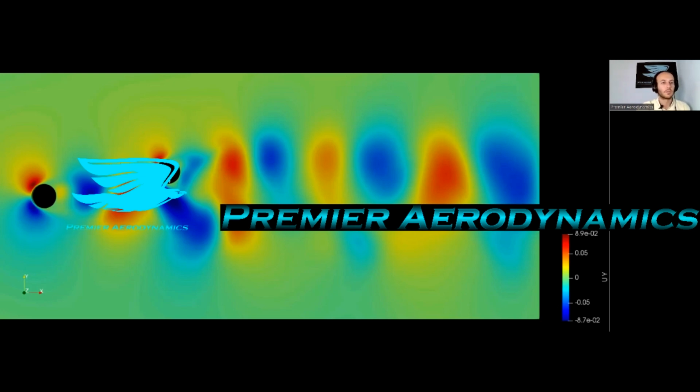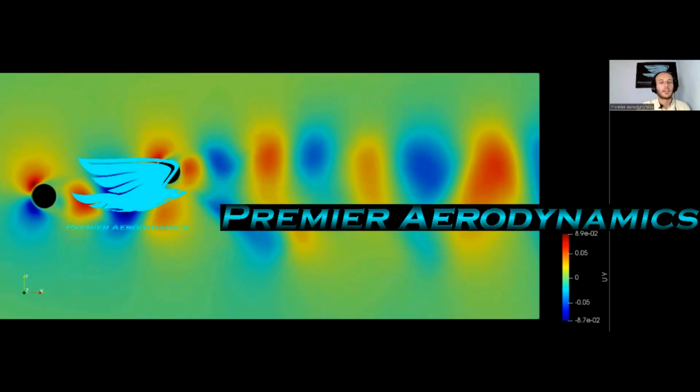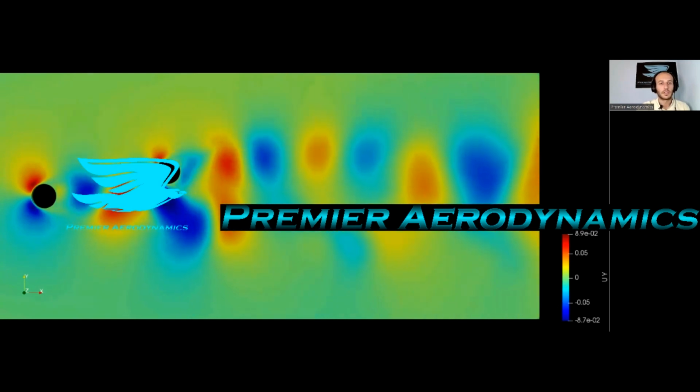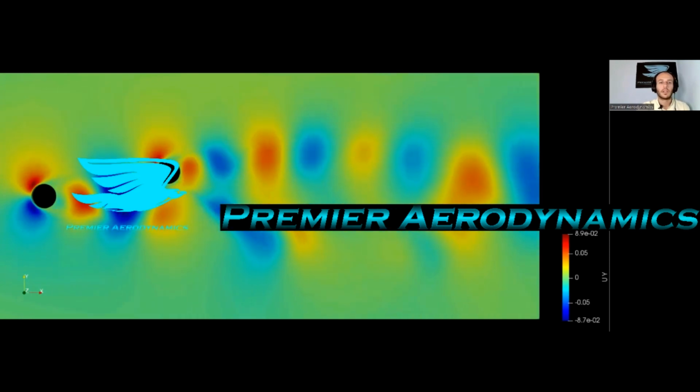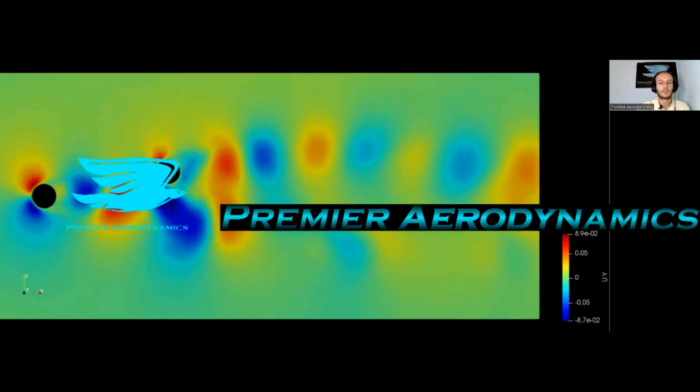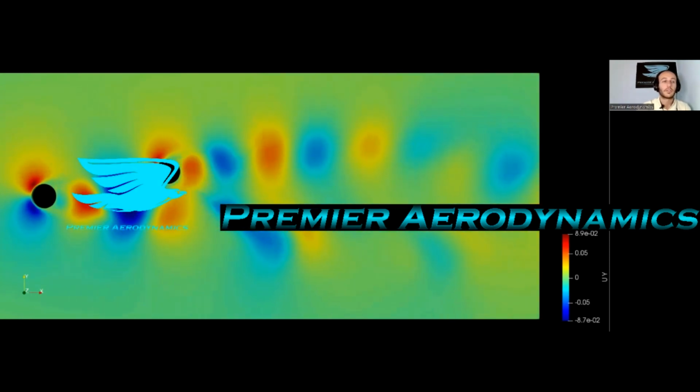So we have the upstream cylinder, the downstream cylinder. And as the flow goes downstream, we can see that compared to the von Karman Street in the first cylinder, the downstream one is not nearly as intense. So you can see how these aren't as high or low. And they're all kind of aligned. So that's this video of tandem cylinders which are misaligned.